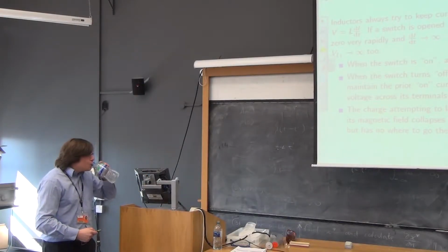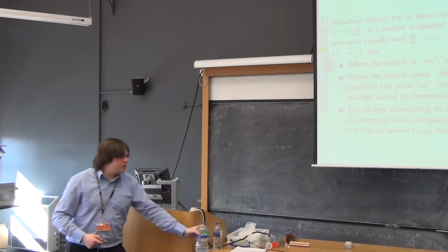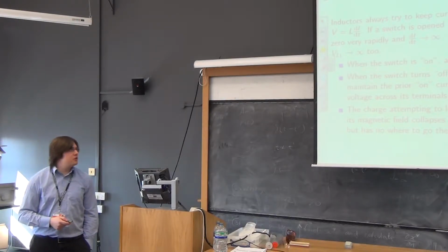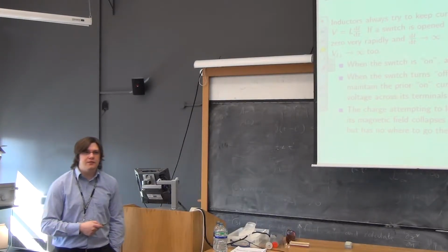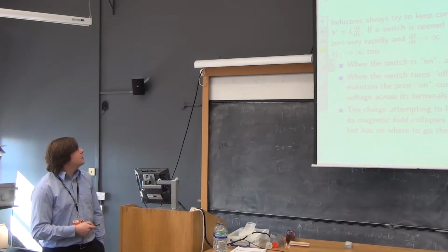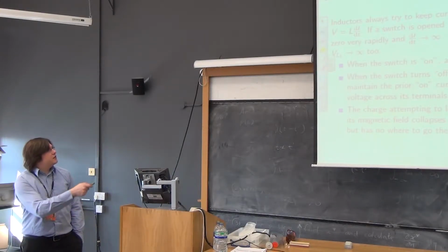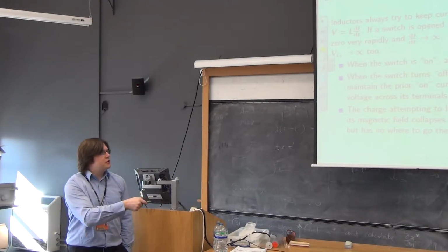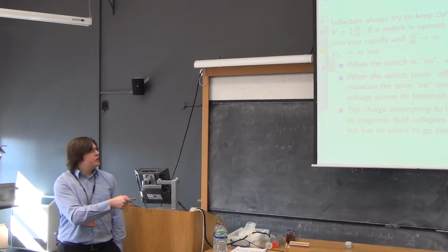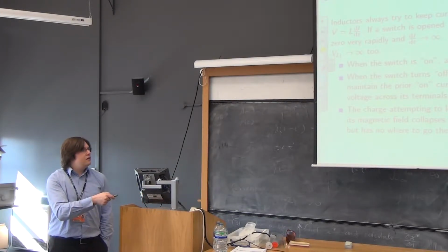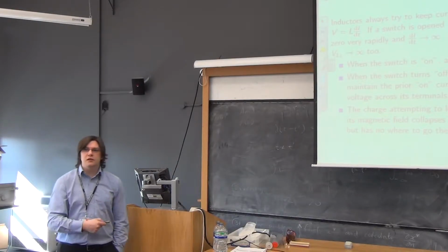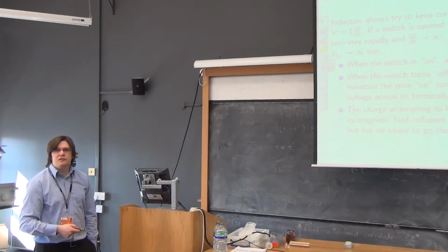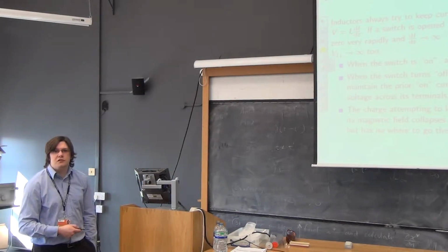So machines are usually inductive loads, and so are relays. And relays are something that we have to talk about in this course, so we need to talk about inductive loads a bit, even if we're not too worried about machines. The principal difficulty here is we've got this inductance and some resistance, which is our load, and a switch, which is ideal. And we have this point A, which is the connection between the end of the inductor and the start of the switch. Now, the inductor could be the coil of a relay, or it could be a machine. It doesn't make any difference. It's essentially the same thing as far as the circuit is concerned.